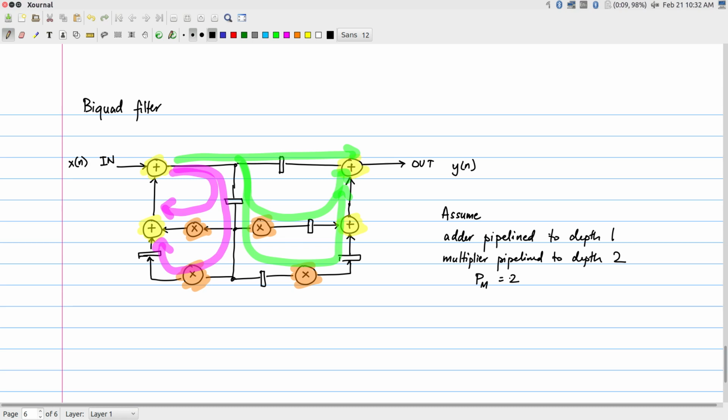So now with this information in place, I'm going to write down S1, which is for the adder. I'm going to assume I have one adder and one multiplier. And before I can write S, I also need to know what value of N to use. What's a suitable value of N? How many phases do I need?